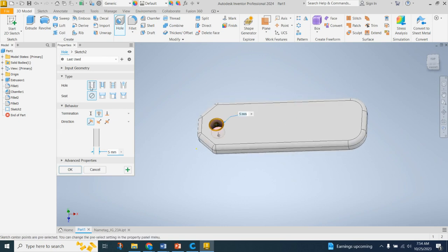There's many shaped styles of holes depending on what fastener you're using and what you need. We're just going to do a simple through hole. That's what this little button right there means, through all, direction downwards. And I want it to be 5, but you can play with the numbers. 1 is way too small. 8 is pretty big, okay? I like 5 because that's ish a quarter inch, just slightly under a quarter. So we're going to go with that.